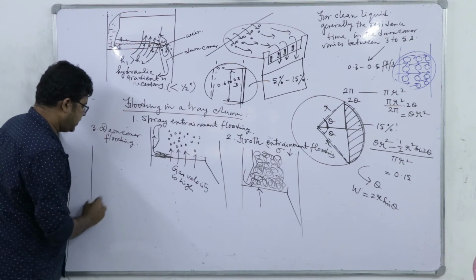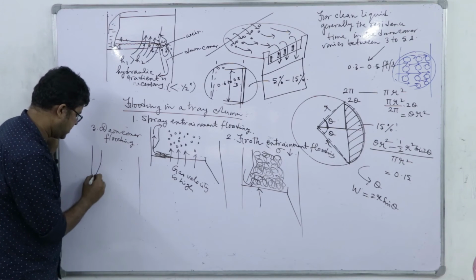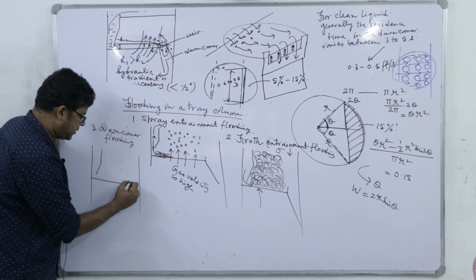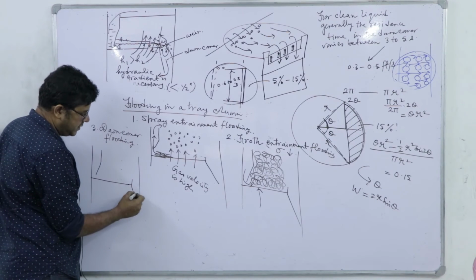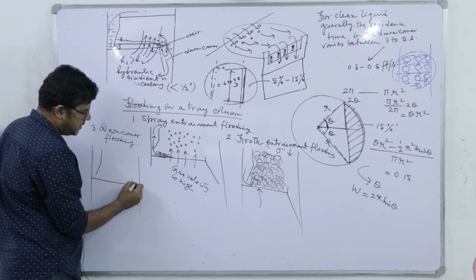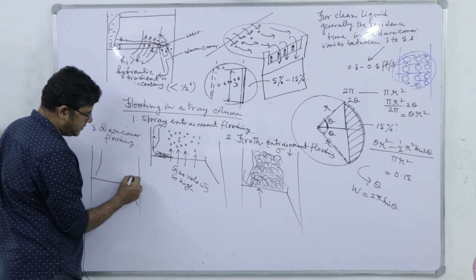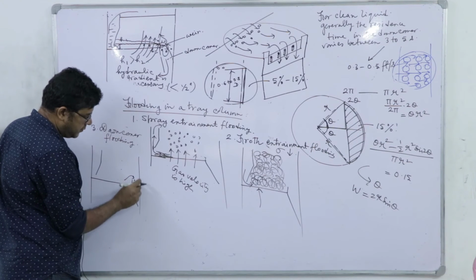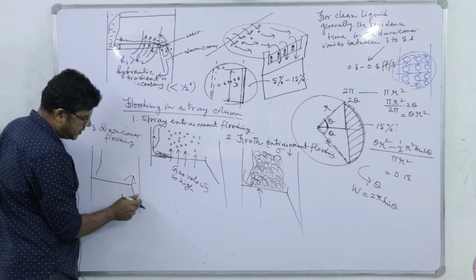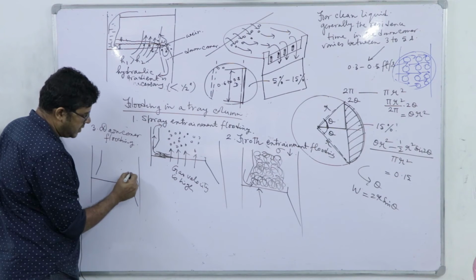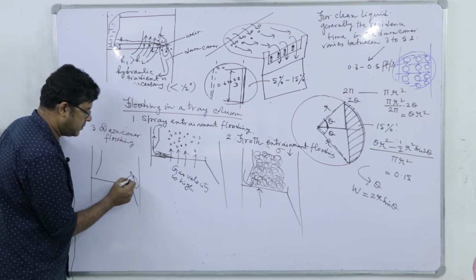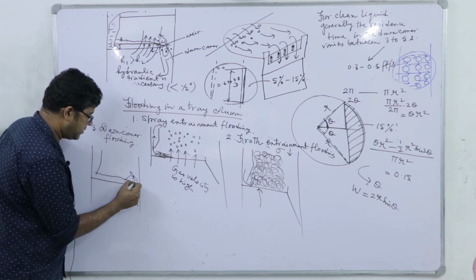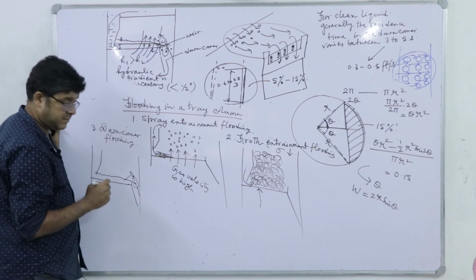Right. See, the downcomer, there is a reduction in cross sectional area as I have mentioned, because the upper part, if any gas bubble is entrained into the downcomer, we have to contract the section, we have to create a bottleneck such that this gas bubble flows out, right. But this at the same time may be leading to flooding, right.